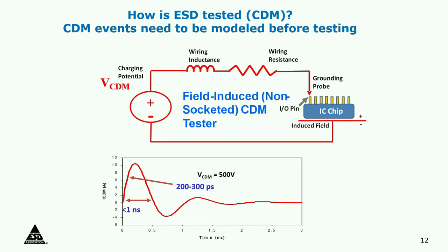current rise in a very fast time, any IR drop in any metal connection, let's say there is something like 1 ohm or 2 ohms of resistance, at 10 amps, at 2 ohms is 20 volts instantaneously. That's the reason it blows up a gate oxide like what you saw.